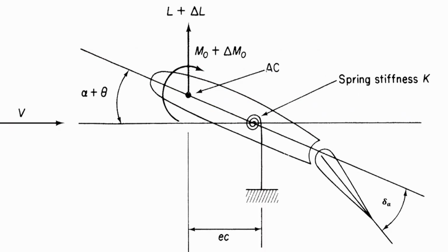So if we take only the cross section of the aileron with a downward deflection, it looks like that. Basically, if we have an undeflected aileron, as you can see, this velocity is the free stream velocity. Because we have deflected the aileron, our angle of attack has increased, right?